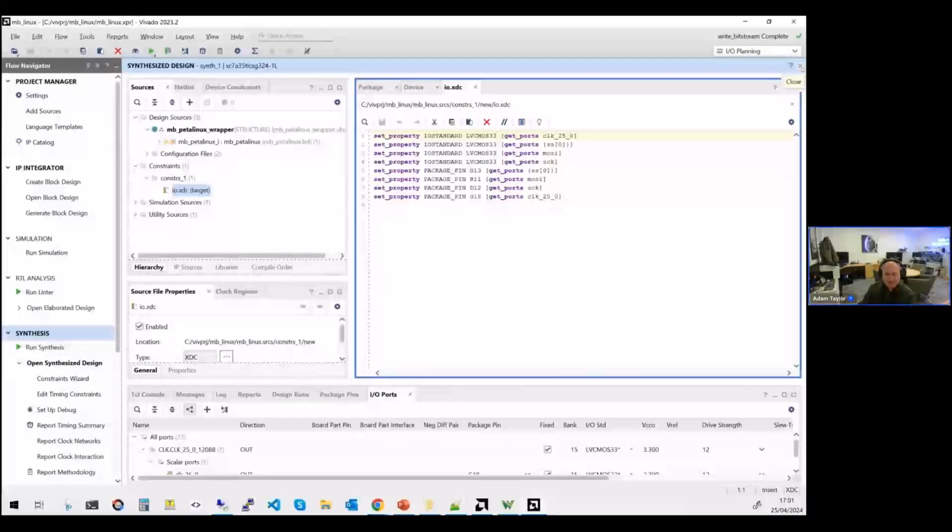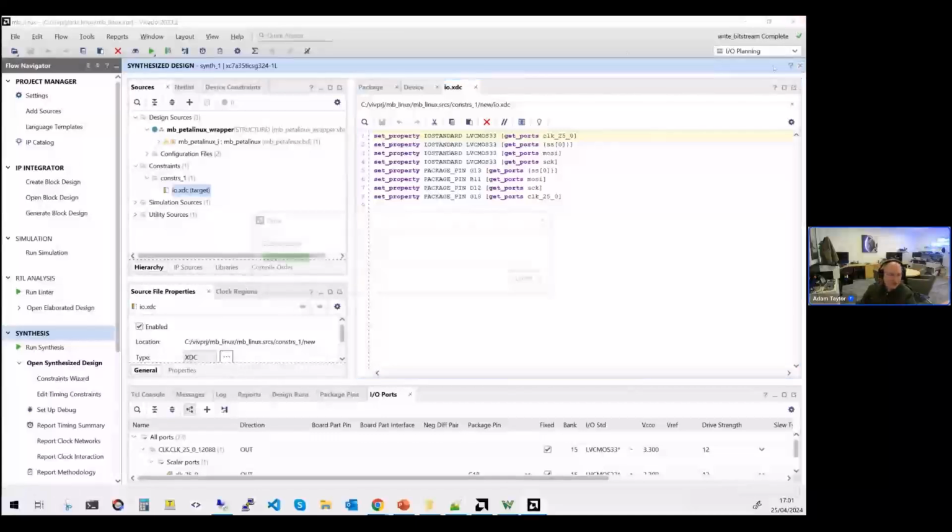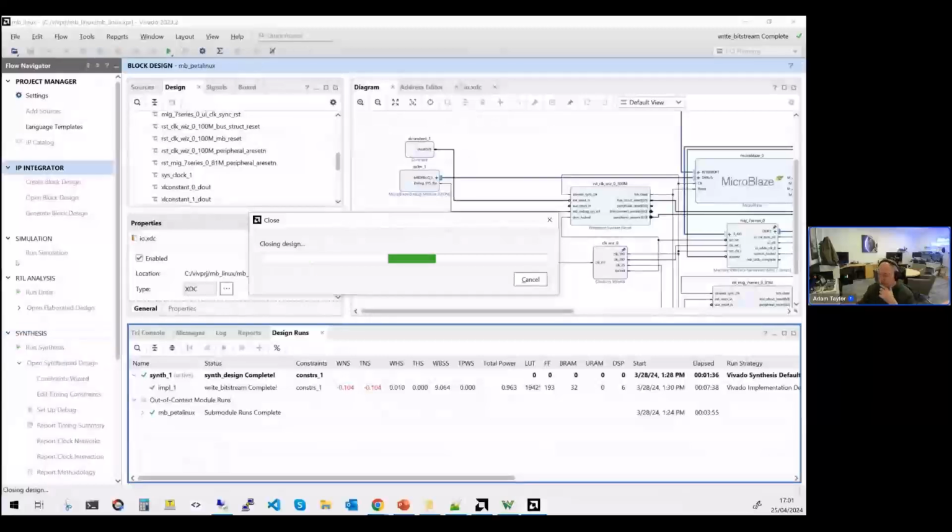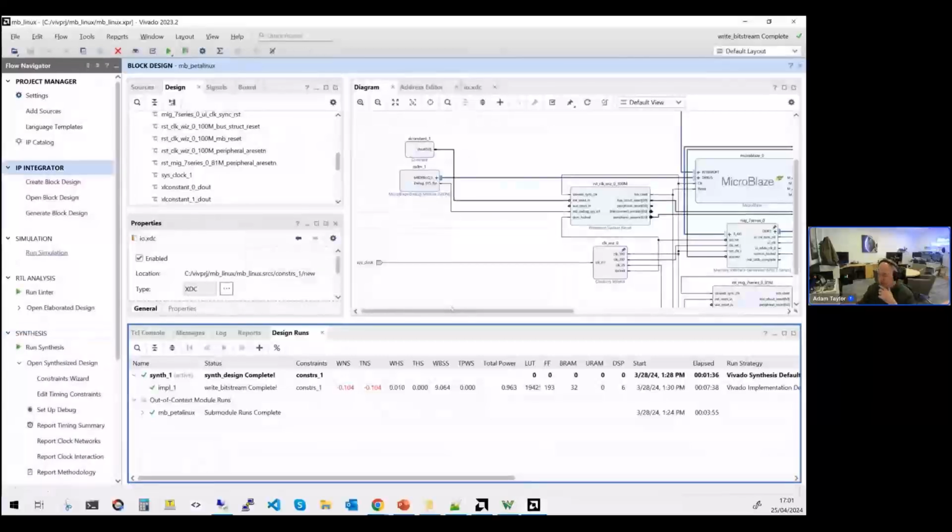So yes, there's an interesting point about the DDR controller interface. Why not use the AXI DMA? You still need to have some physical something implemented that implements the protocol that the DDR uses. So in our system, for example, if I just close this design here, if I wanted to do DMA into and out of the MIG, where is the MIG?